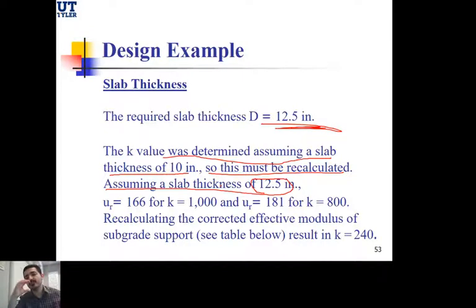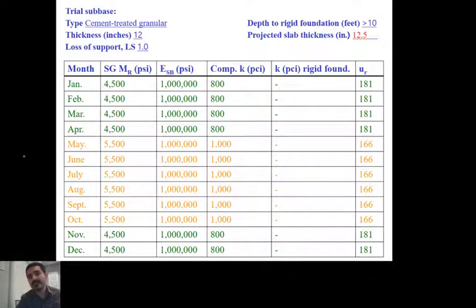But again, if you have that question in mind, yes, when we design the PCC structure, we assume a certain thickness of the PCC layer and a certain thickness of the subbase. The subbase doesn't change, it's going to be fixed, but with the iterations, we need to keep changing the thickness of the PCC layer. So what is this going to impact? It's going to impact this column right here only, because again, you're going to repeat the entire table one more time.